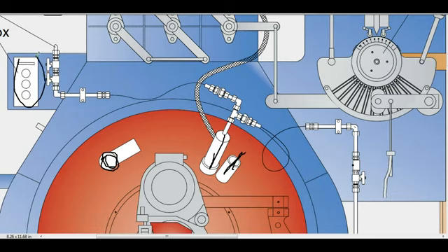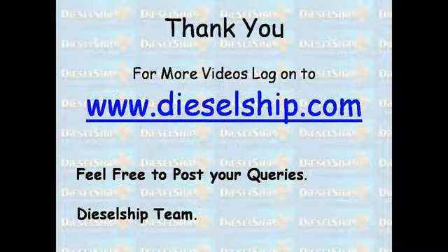Wow, let's see what this is. This is a junction box for manual operation or emergency operation of the boiler. To operate the boiler in emergency, what you have to do is disconnect the servo motor, and there is a manual handle provided here to operate or adjust the fuel cam or the compound regulator. So this button is for increasing the compound regulator, and this button is for decreasing the position of the compound regulator, and this will be for ignition of the pilot burner or the igniter. So the position depends on the design of the boiler. So that's it.